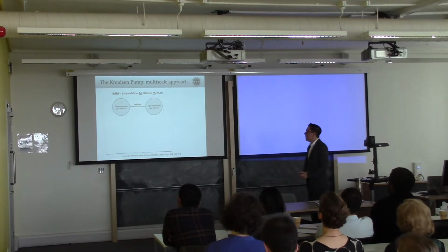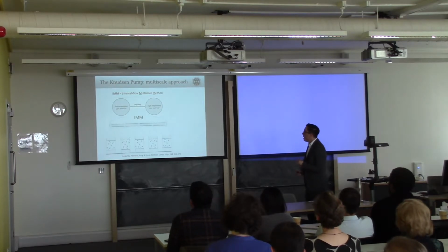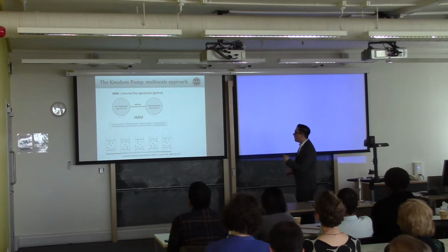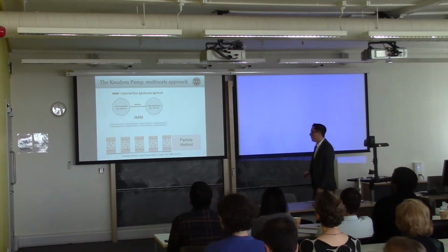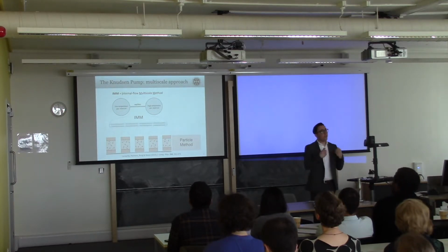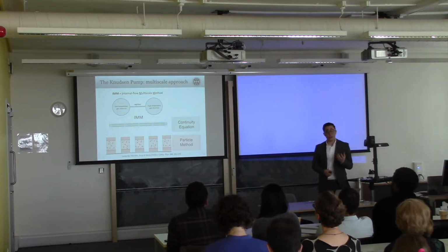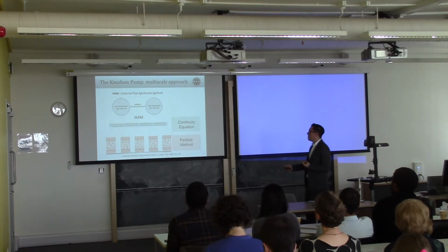So the way we've solved this is by developing that high aspect ratio method, which we call the internal flow multiscale method. Basically, we treat the most problematic element, which is the IMM, where the non-equilibrium effects happen, and we slice it by applying individual particle simulations at different slices of our filter. At the moment, these particle simulations feel they're unconnected to the other particle methods. So you need an overlaying method, let's say a conservation of mass and/or energy in this case as well. And so now they realize that they're part of a system. So these methods are now going to transfer information.